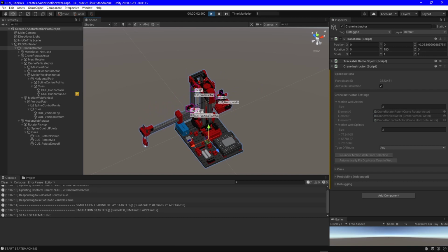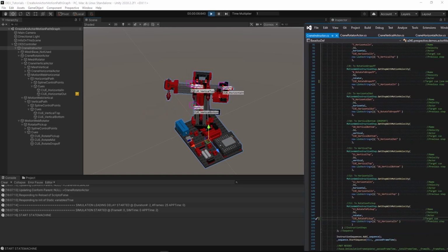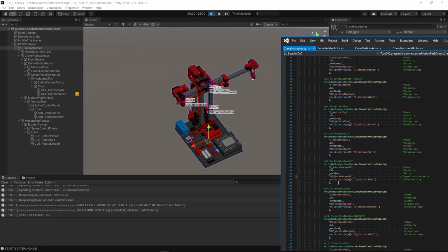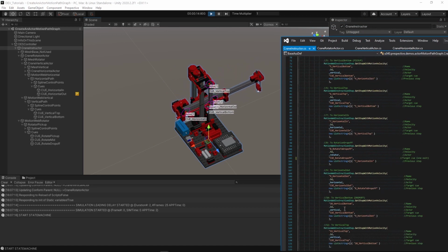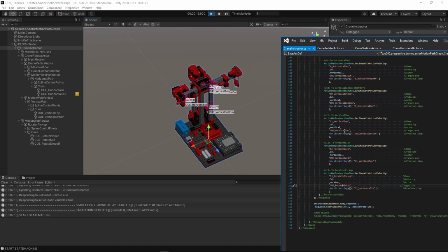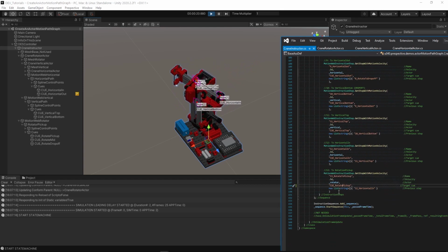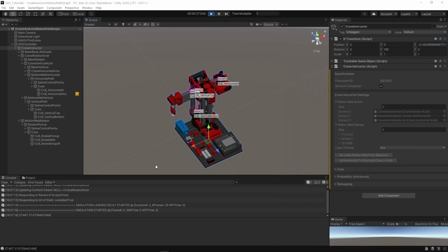So now you see we are walking through the state machine. Yeah, the steps, we're now rotating to the drop off actually already. So rotation to drop off, step number 8, going out, going down, going up again, going in and rotate back to pickup, and then it will just stop. So it will not start over again. So it's doing what we would like to see.